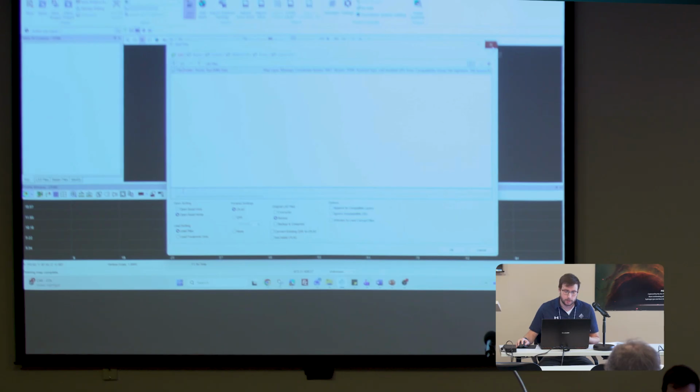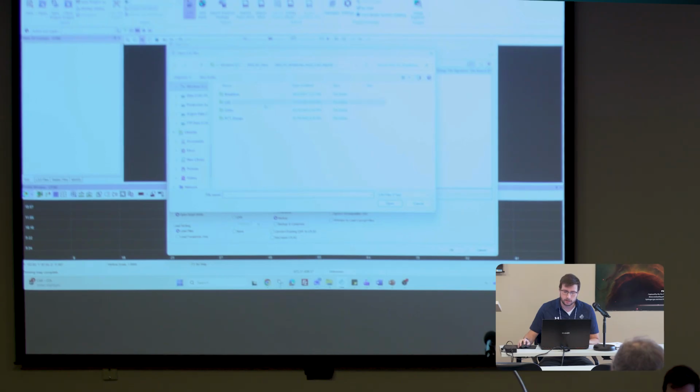And like I said, we open up LP360. Let's click on the Add Files dialog here at the top. Click on the LAS tab here in the top left. Click the plus button and go ahead and add those LAS files. Again, they're going to be not LAS files, but LAZ files, compressed LAS files, and we'll select those. It's this little option here in the bottom right, switch that to LAZ, select the files, and click Open.